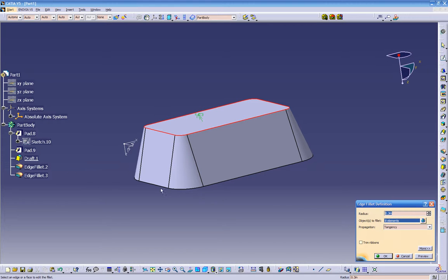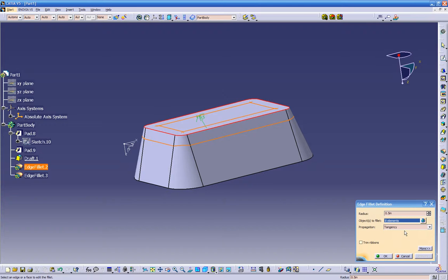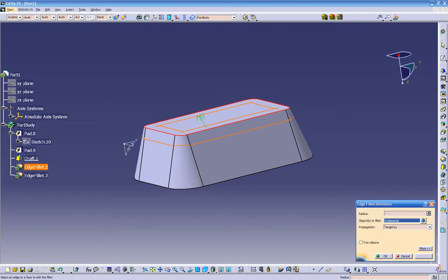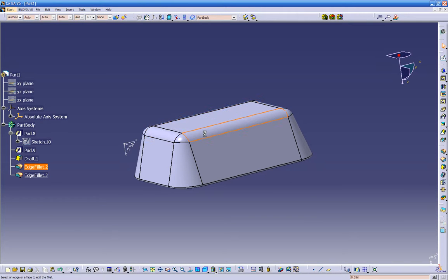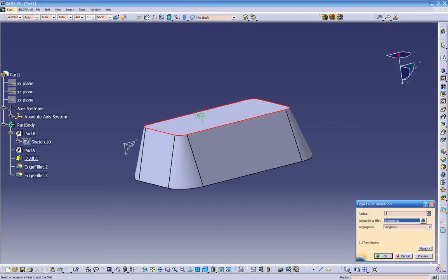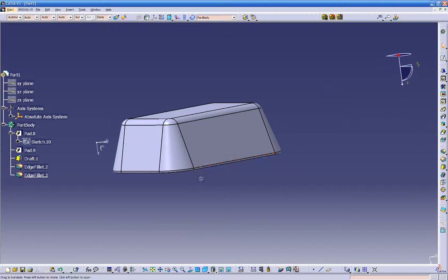Double click on the fillet, same thing, we can change it to 1/2 inch. Let's do a preview. Oh, it's just too big, so it doesn't like that because it overlaps. So let's make it a little smaller. Let's make it 350. So that's a little radius, still too big. So let's make it 300. Actually, let's get a little smaller, 250. Click OK.